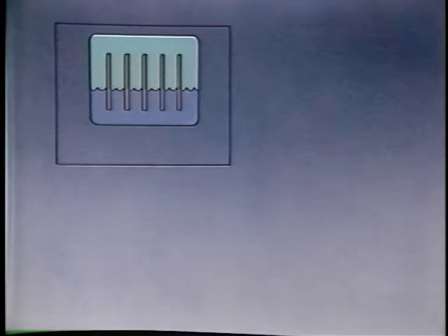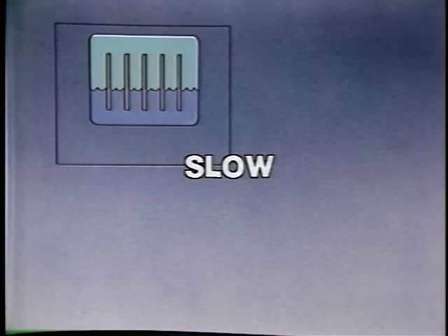The wetted element method supplies water as required by level setting switches in the pan. Evaporation, however, is totally controlled by the passing airstream and therefore dependent on heating requirements. Evaporative pan humidifiers turn on when commanded, but the water still must be vaporized in order to humidify the air.